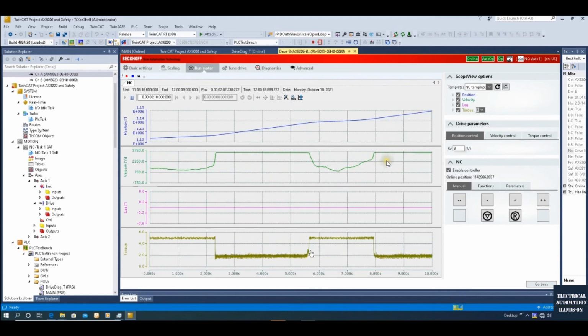So using this curve, we can imagine we are using this motor running as a rewind, the rewinder. The highest torque from the motor will be only 5%. The motor won't break the web, and its velocity can be limited in a certain range. This is the typical curve while we are using the torque control mode doing the rewind, especially for the case where the diameter cannot be measured accurately, and the velocity will be dynamic according to the actual load.